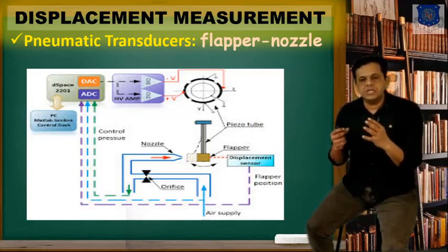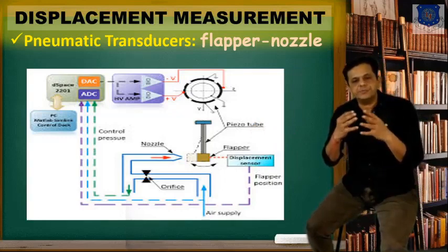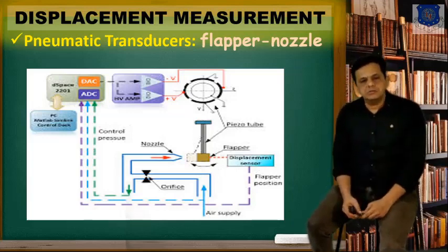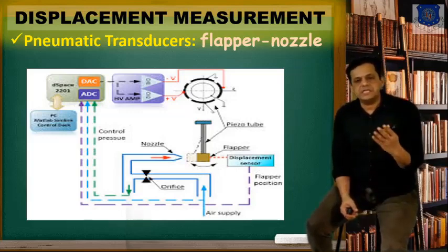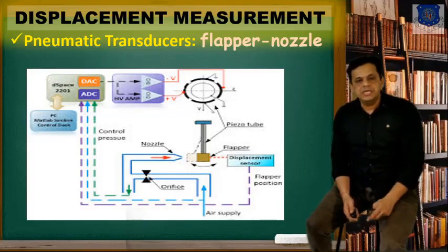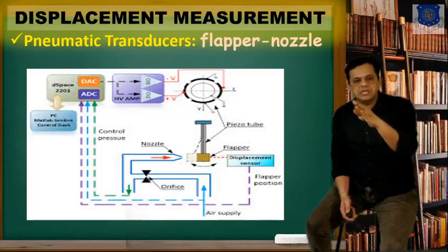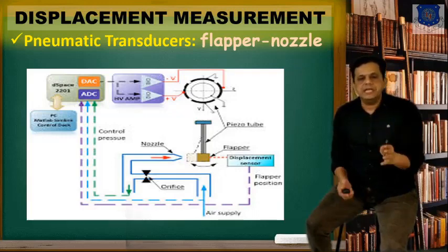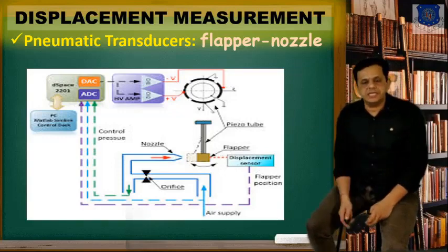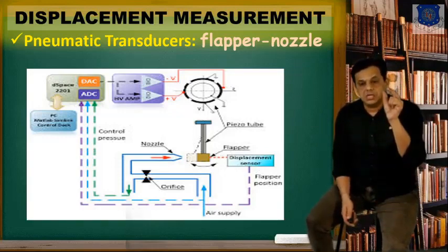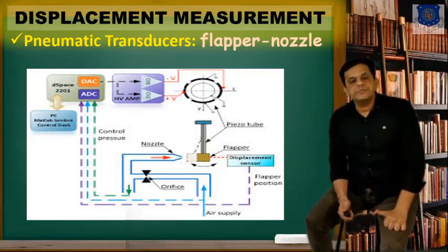So those vibrations will create the respective voltage signals, and ultimately we say it is the secondary measurement we are doing here. And the entire circuitry is created that will be converted to some analog signals, and then a DAC is employed, and the entire closed loop system is created for the measurement of a very small displacement in terms of X.